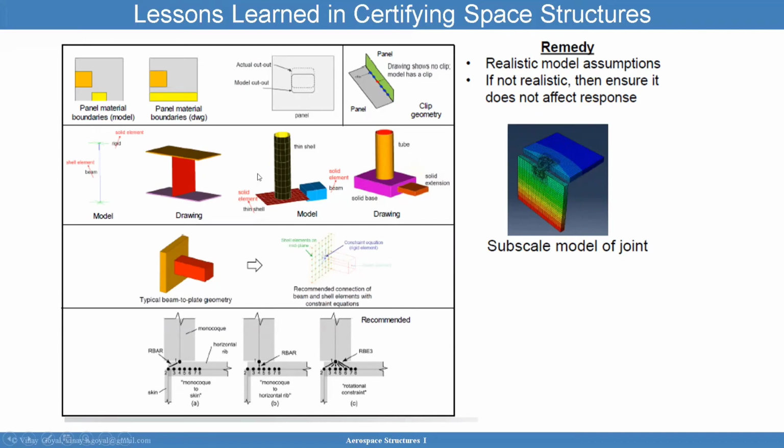Say you have this as a drawing, and you can see here clearly that this looks more like a shell. Well, if this was modeled as a beam, that's incorrect. You can see here at the top it looks very different, but it was modeled as rigid. You probably want to use shells or solid elements. So you can see here there's a big difference between how you model something, how you represent and simplify a drawing into an accurate physical representation.